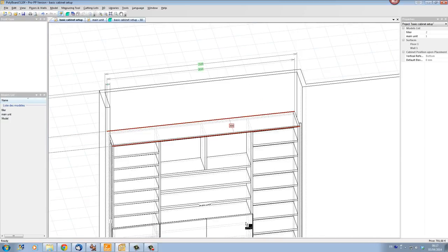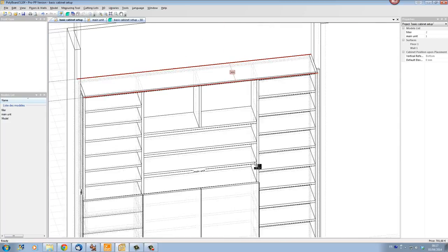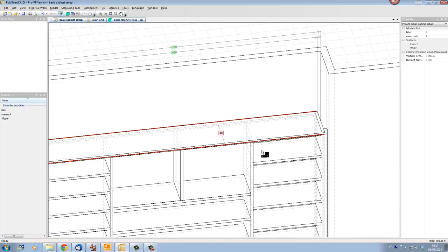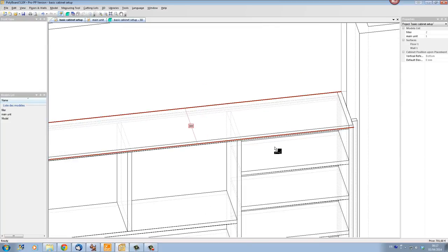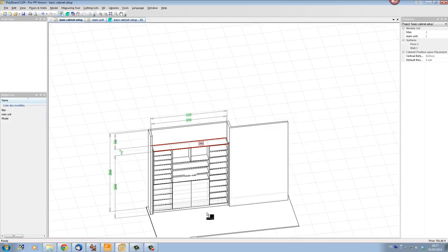This is because this cabinet has two doors. We have a look at the doors here, and these doors have a certain thickness which are setting back the main cabinet shelves, main cabinet parts, by the thickness of the door, and the significant edge which the measuring tool is using is actually the outer limits of our cabinet, so be aware of that. We're now using here the outer limits of our cabinet.